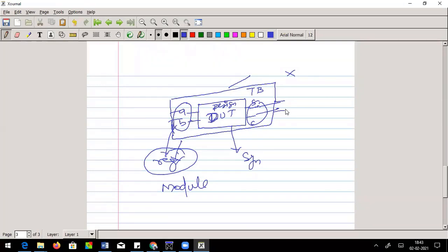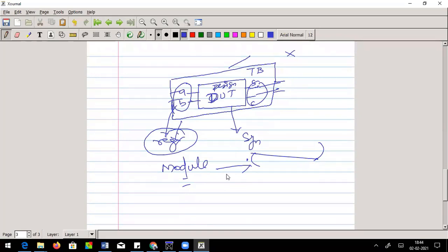That's the main change. So for the module, you can give a module name, same idea. You can have a port list, or you need not even have a port list. Go there and define your inputs and outputs as usual. Then instantiate your design inside this test bench, because you are supposed to use this design under test. For this design under test, say a full adder, I am calling full adder F1 with all the corresponding port list.